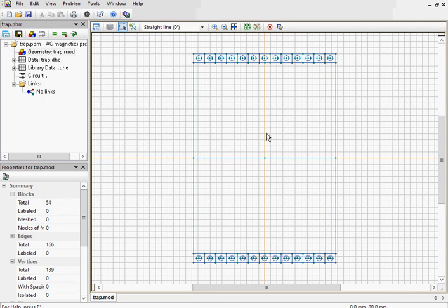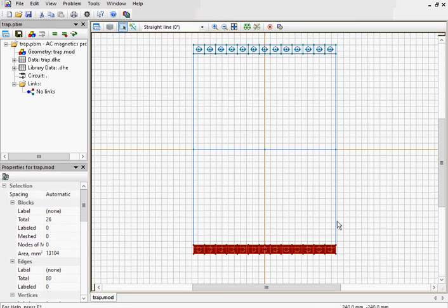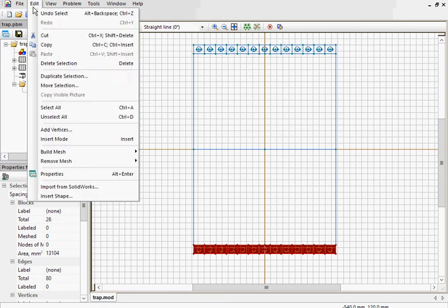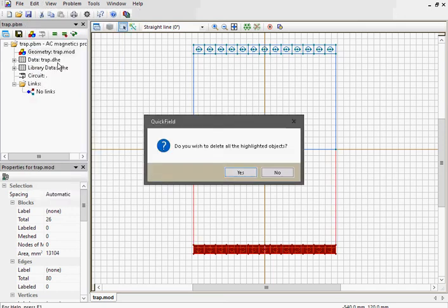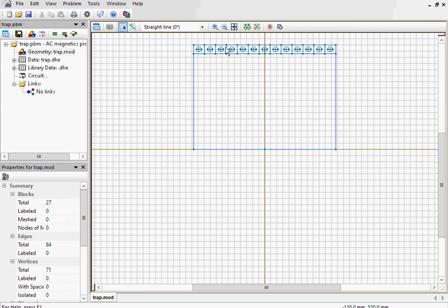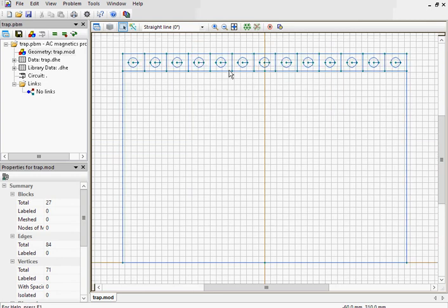In the axisymmetric problems, the axis of the rotation is a horizontal one, and we should draw only the upper half of the cross-section. So switch to select objects, select everything located below the axis, edit, delete selection. Yes. Now here you can recognize fiberglass case and aluminum cable.